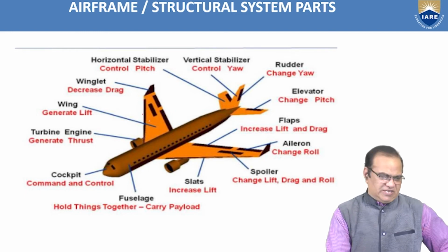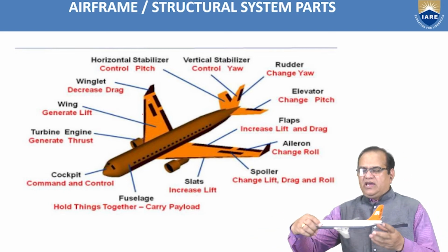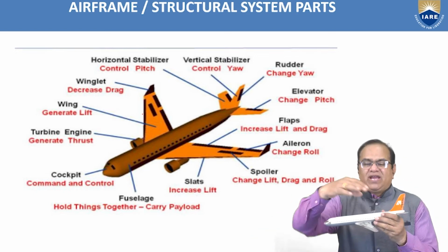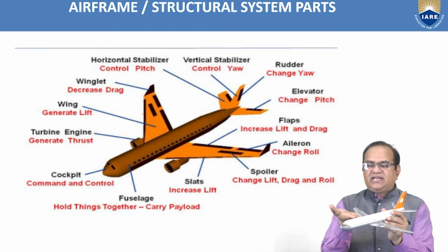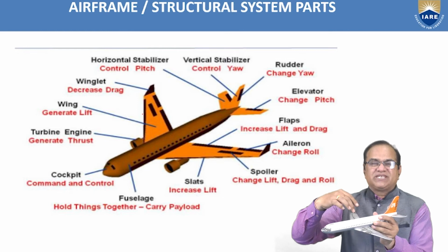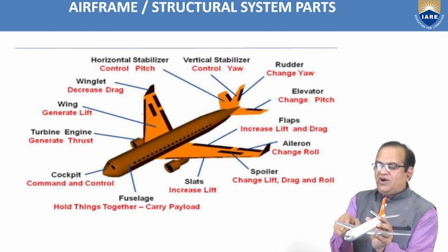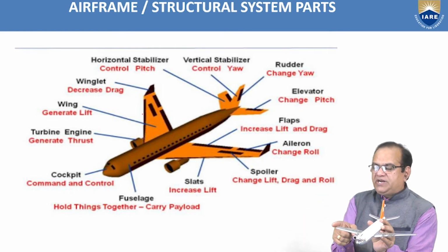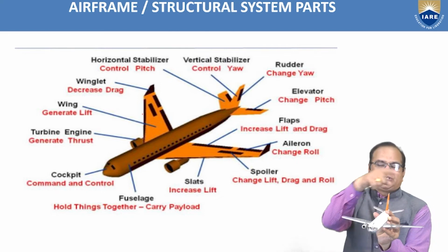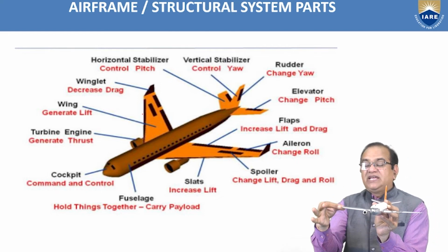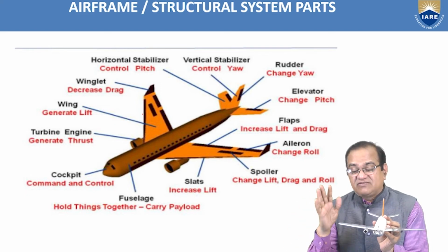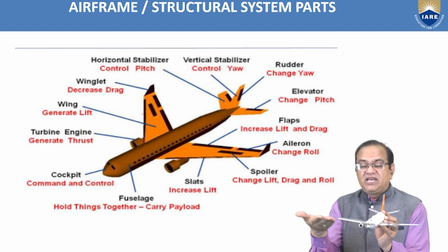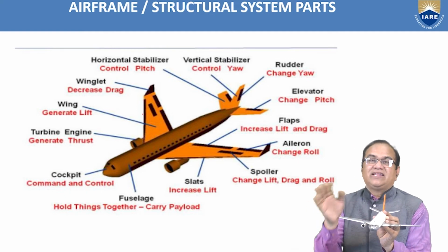And the lower surface, if you see here, I will explain. If the winglets are here, like this, here the pressure is high and the upper side pressure is low. So as vortices are formed from the tip, it will go like this. Both sides, it will rotate like this. This will generate the induced drag. Additional induced drag is generated due to the pressure difference between the lower and the upper surface.